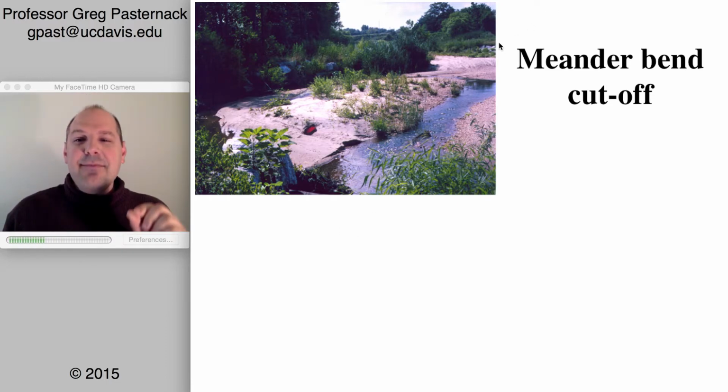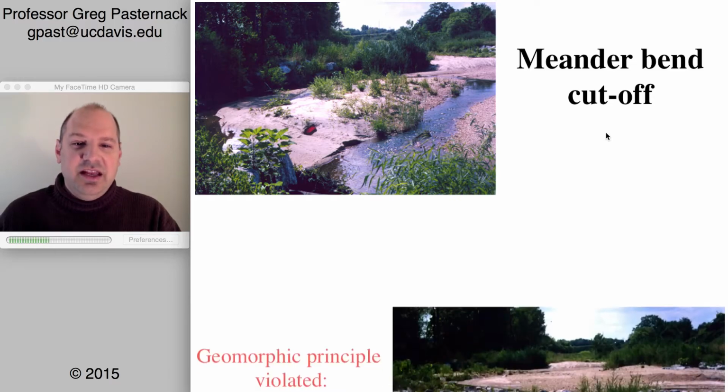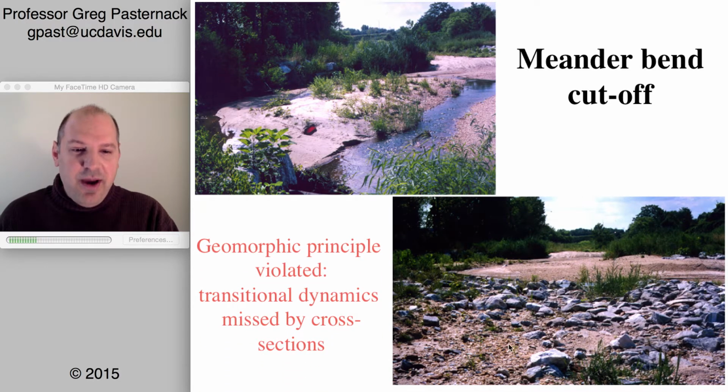Now, let's not mistake this for a river choosing to do what it wants to do and therefore creating the correct shape. We have a degraded river that's been changed to a new degraded form, and the river is behaving in a new degraded way. You could call it a natural response, but it doesn't mean it leads to a natural outcome. So the solution that they did here was that they just came in and riprapped every single meander bend to prevent that from happening. When you force a channel into a shape, it's no longer a river channel, it's what I would call a flume.